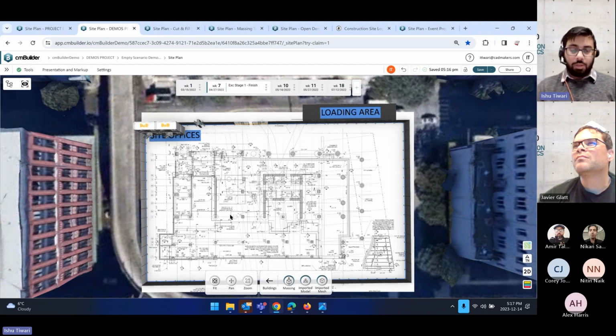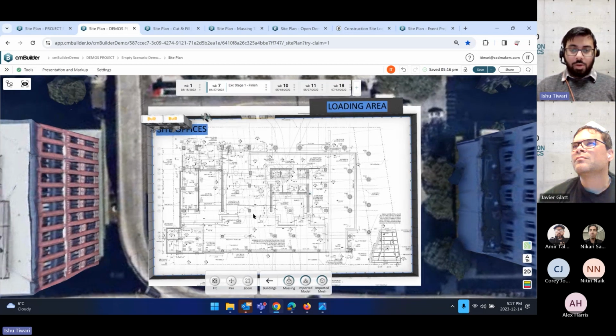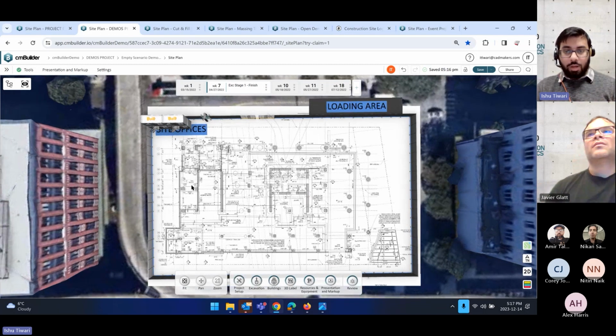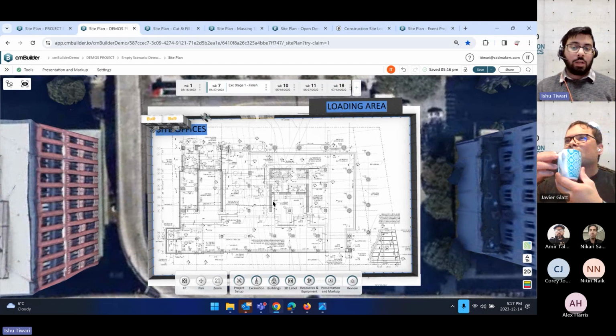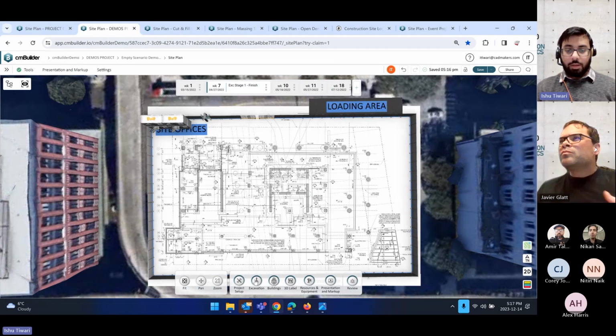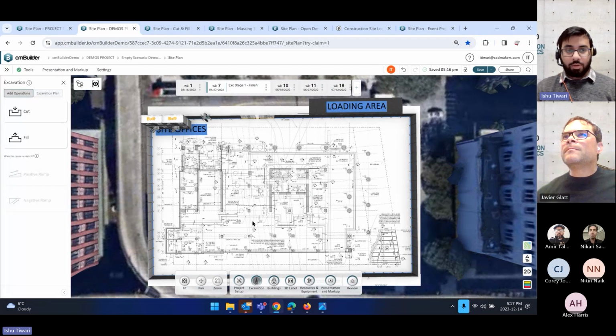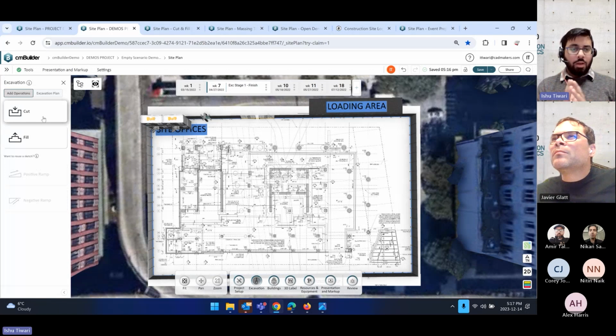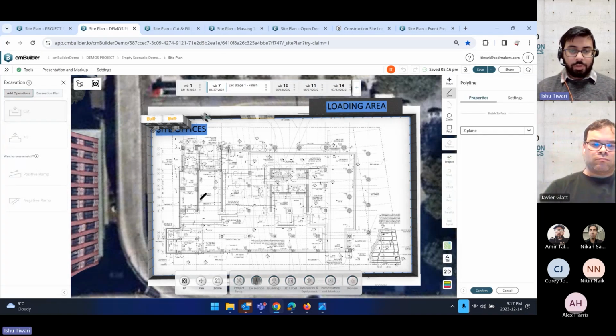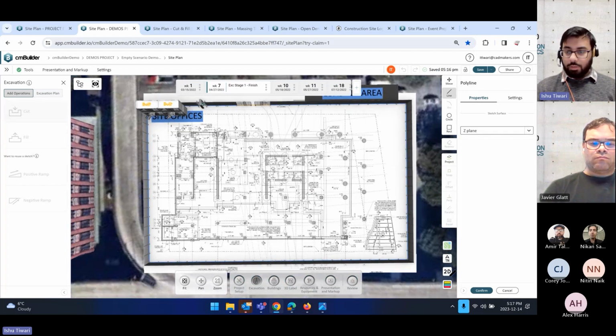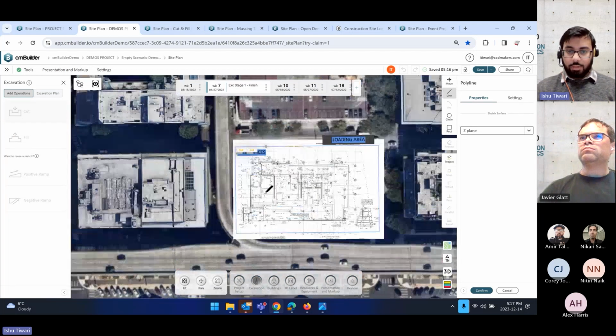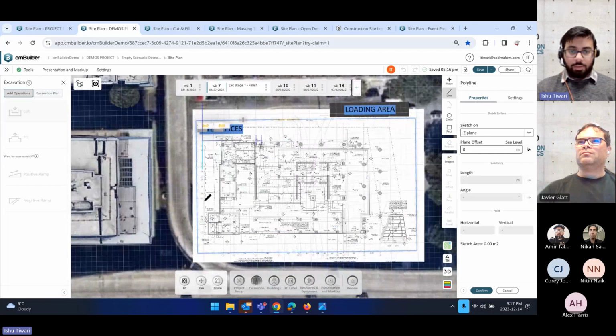It's a very popular tool in here. So the way it works with excavation, ideally you would be swapping this drawing. You will be bringing in a geotechnical drawing to use for excavation, or its foundation drawing. You can create your cuts, fills, and ramps. So those are the three main operations with the excavation tool. And let's go in a 2D mode. It's way easier and quicker as well, and more accurate.